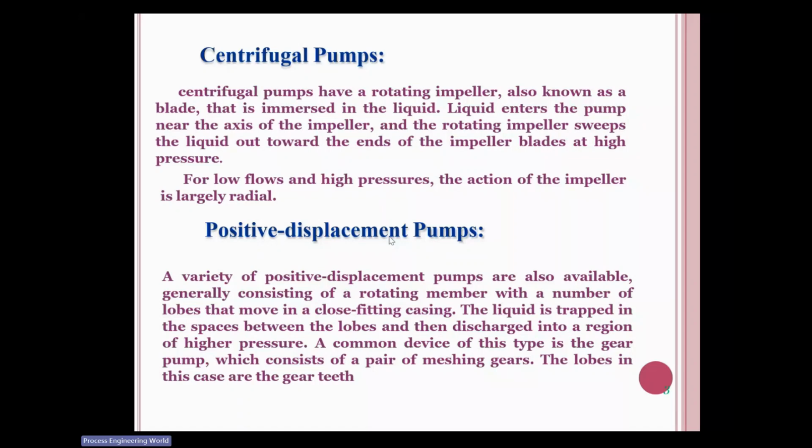So what will happen? Pressure can reduce a centrifugal pump's delivery. It means in centrifugal pumps, pressure can reduce the output, and high outlet pressure can stop any output. The liquid simply recirculates inside the pump. What happens in a PDP is completely different. The pressure affects the output only to the extent that it increases internal leakage. What actually is the difference?